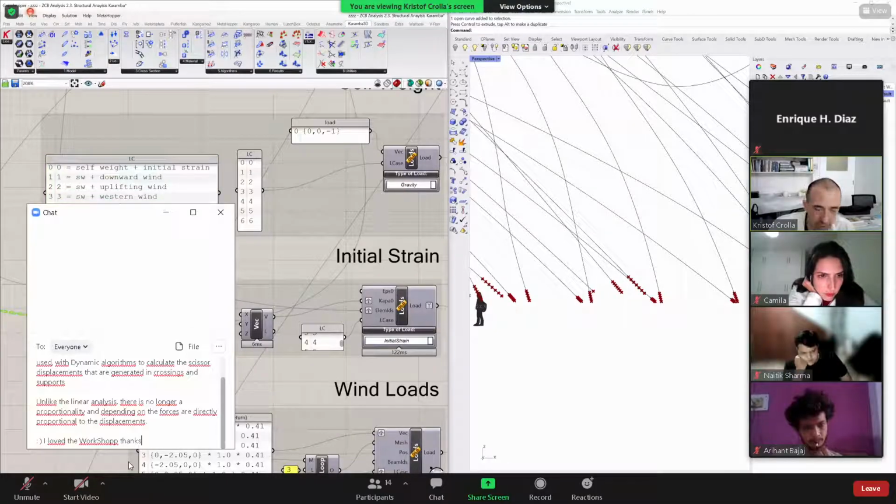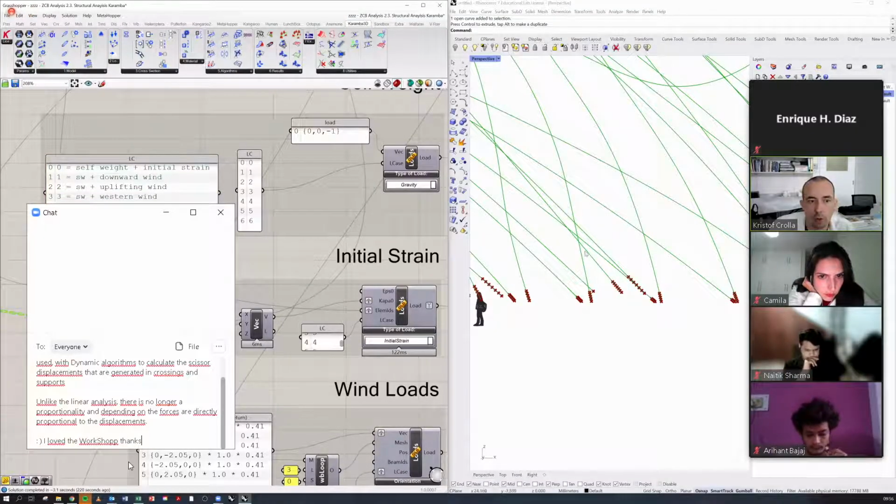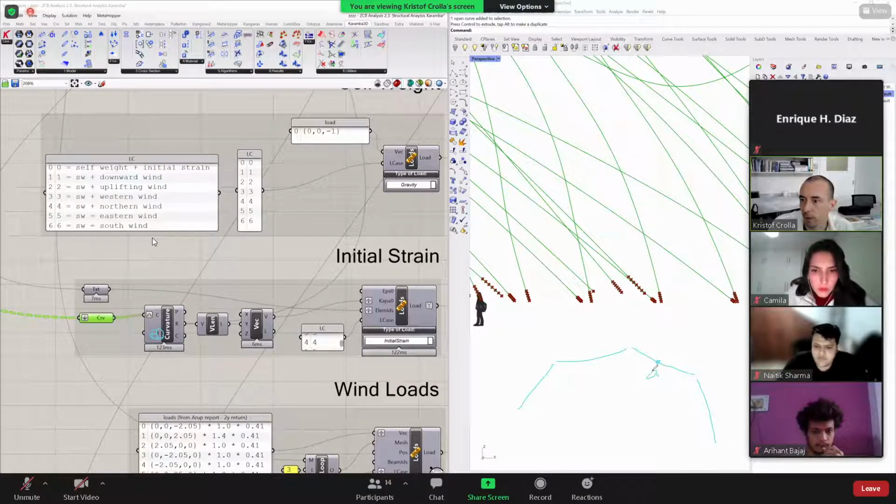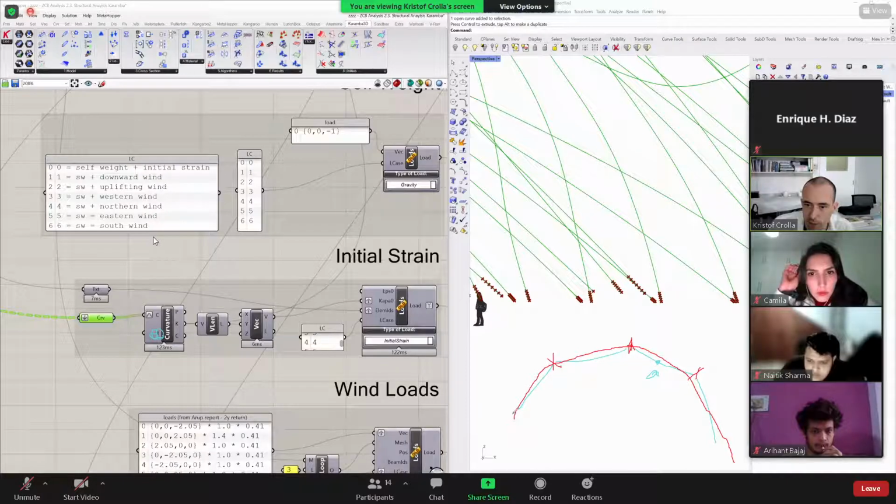So that's why it's important that the input that is given here in your curve, in your model, is that those are curves, not polylines. Because if you abstract your model to polylines, say, and then you evaluate at parameter 0.5 what your curvature is, for all of these points, your curvature is infinite, right? So you need to make sure that for the Karamba models that you work with a smooth, continuous curvature setup that of course still intersects with all the points that we have here. So we're gonna have to redraw that a little bit. And then you can segment it if you want to as well. But basically the curvature analysis that you'll do in the middle of each and every one of the segments cannot be or should not be infinite if you wanna have a loading here.